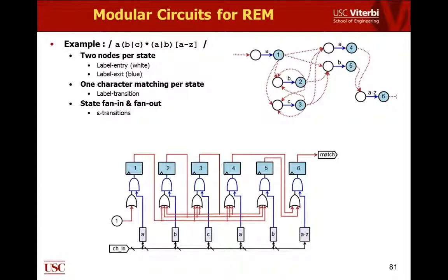What we do is that all these states I am showing here in blue, we'll map those states into the individual flip-flops I have in the FPGA implementation. And all these connection logic you are seeing essentially is capturing whatever connections you have here. Just a simple example, if you look at state number 3, the incoming edge here is C. Therefore, for state number 3, it's the input character. I decode that by using this AND signal here.